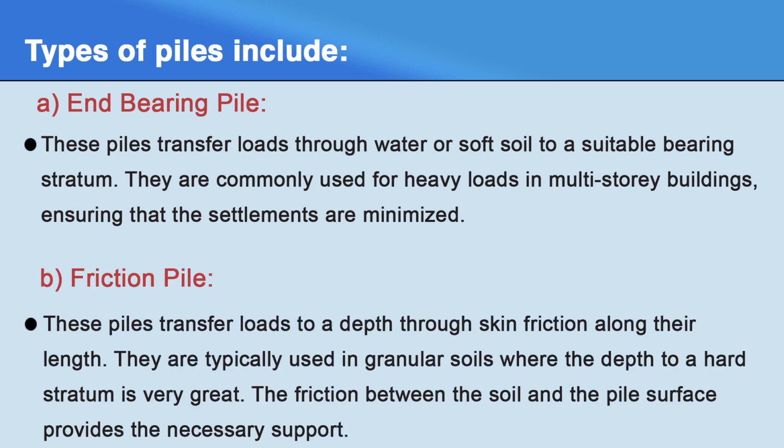Then the next is friction pile. These piles transfer the load to a depth through skin friction along their length. They are typically used in granular soils where the depth to a hard stratum is very great. The friction between the soil and the pile surface provides the necessary support.